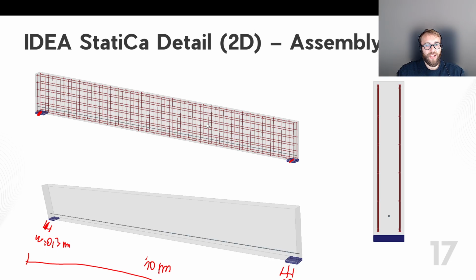There are also populated the reinforcement rebars. There is also accommodated the part of the tendon that is embedded inside, and it looks basically like that. It's a 2D plane stress solution, compatible stress field method. Again, same physics, but a different approach.